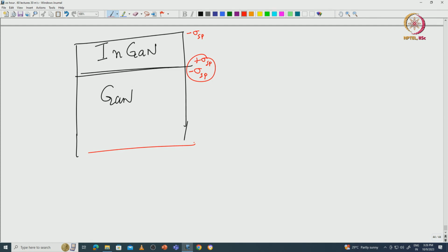However, if you grow a thin layer of InGaN, here is the context. Indium nitride has a huge 11% lattice mismatch with GaN, which means you cannot grow InGaN as easily as you can grow AlGaN. InGaN will relax, and the material quality will be poor because it is also grown at a lower temperature, otherwise InGaN will decompose.